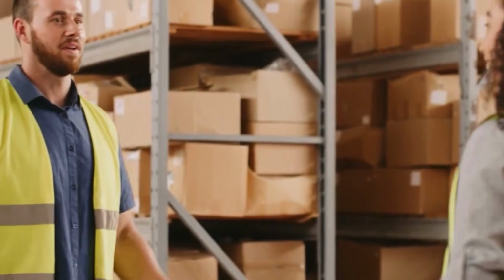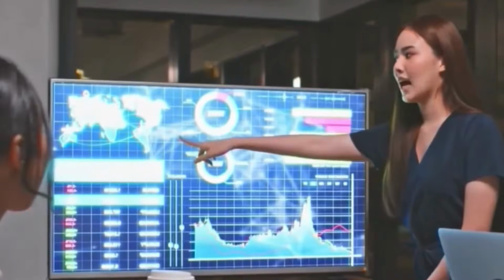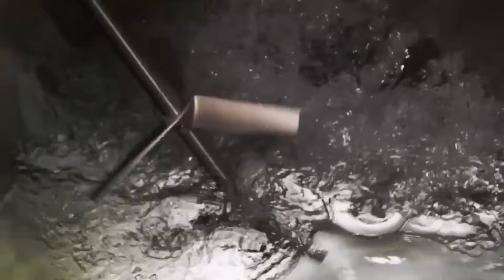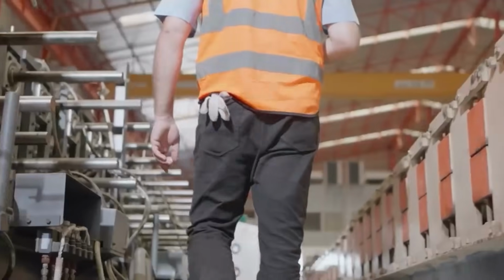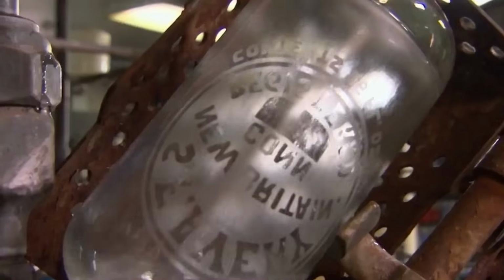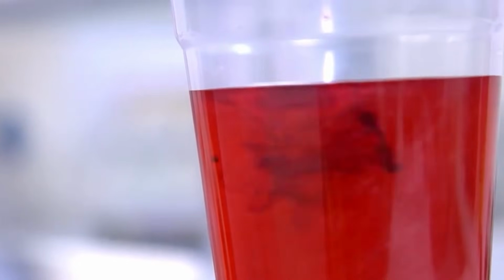Inside a sealed stainless steel vessel, the beverage is chilled to near freezing temperatures to increase gas solubility. Liquid carbon dioxide is injected into the drink through a diffuser plate with thousands of microperforations. The gas dissolves rapidly under high pressure, saturating the beverage with carbonation. Rotary carbon pumps recirculate the liquid within the chamber to ensure uniform CO2 distribution. Carbonation levels are continuously monitored by inline gas volume analyzers. The carbonated beverage is held in pressurized buffer tanks awaiting transfer to the filling line.